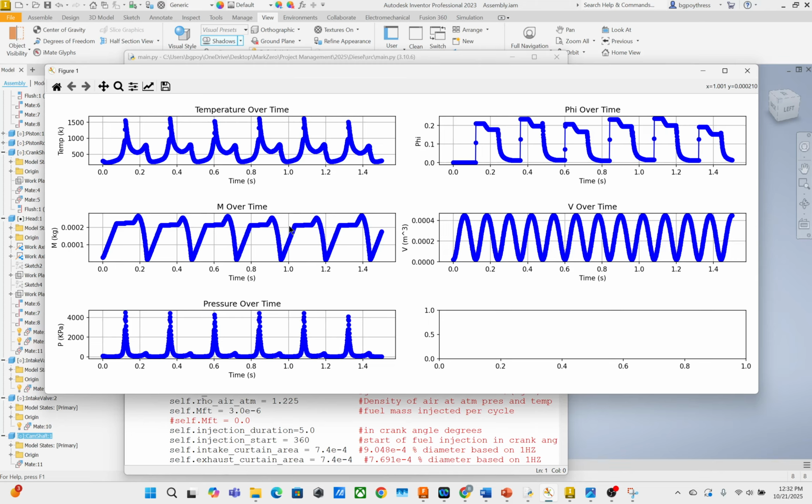And the reason this was done is because by injecting fuel into this chamber with only a little bit of air in this chamber, the burn starts rich, which reduces the nitrogen-based pollutants. And then as the burn travels down into the cylinder, and the cylinder then moves down as it's expanding, it slows the burn down, and so the burn becomes lean and burns up all the soot. So by doing it this way, it gave the engineers a bit of an edge to try to reduce pollutants.